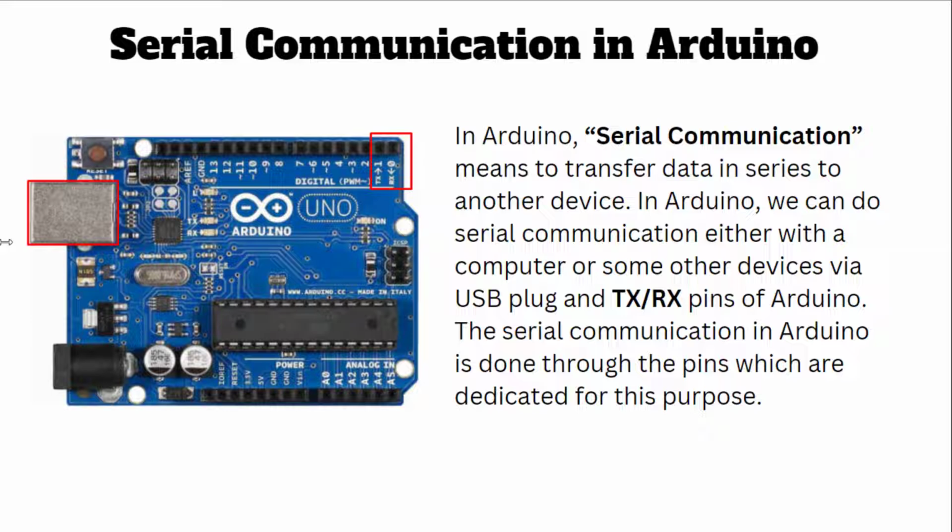Now these circuits provide special input-output pins for serial communication. For serial communication, all the data transmission is handled by the UART, the Universal Asynchronous Receiver Transmitter, but we have to configure it before receiving and transmitting data.